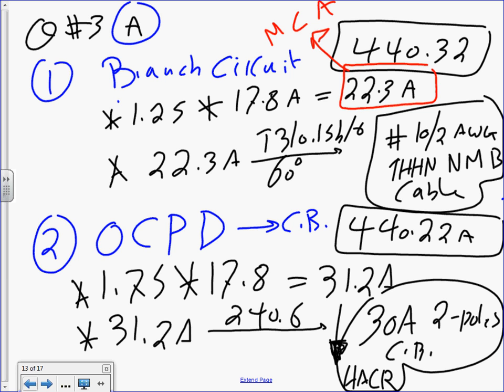One more time. See that math that we did here? This will be done by the manufacturer for you, and they will print this on the nameplate, and they call it minimum circuit ampacity. So you shall not do the math. When you see minimum circuit ampacity, what do you do? Grab that number, like I did here, and size the conductor. Can I have thumbs up, Chad? We understand that one? Okay.